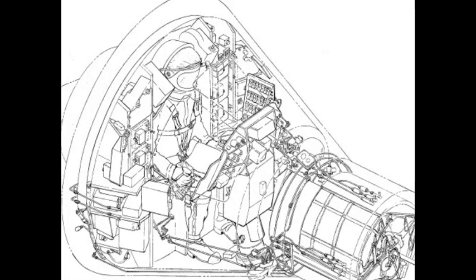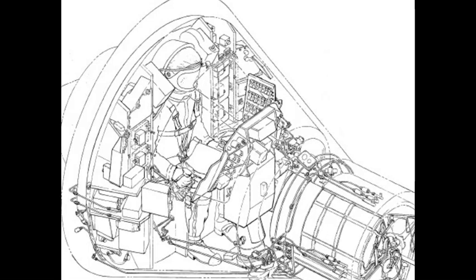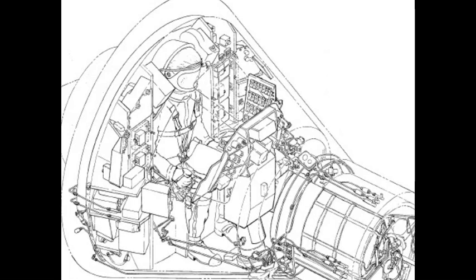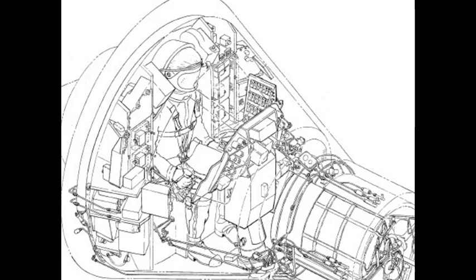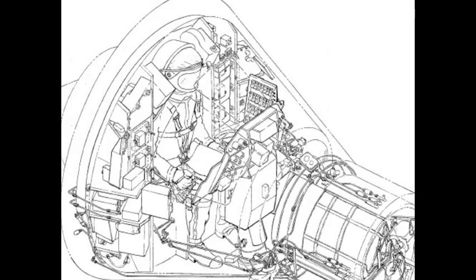Prior to capsule launch, the hatch is bolted and sealed into position with bolts, and 2 corrugated shingles are installed over the hatch. The bolts are inserted through entrance hatch sill, which incorporates the explosive charge, and threaded into the capsule sill. A magnesium gasket with inlaid rubber forms the hatch seal when the hatch is bolted into position.